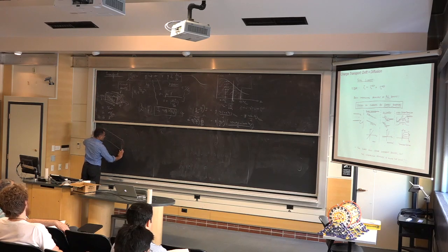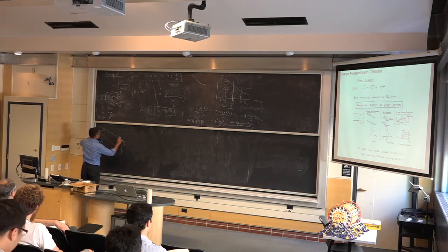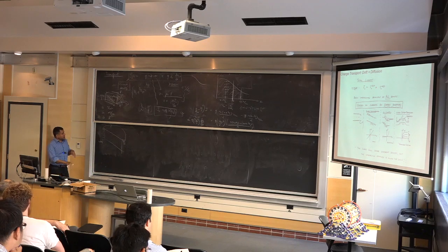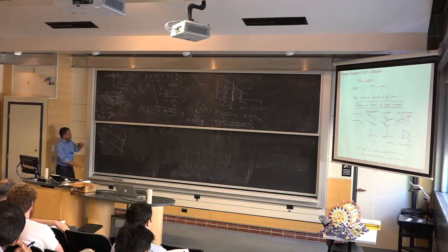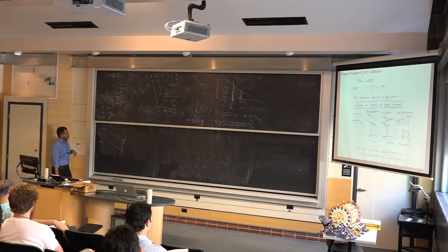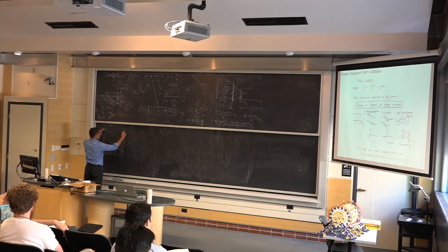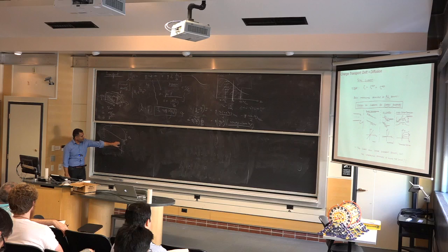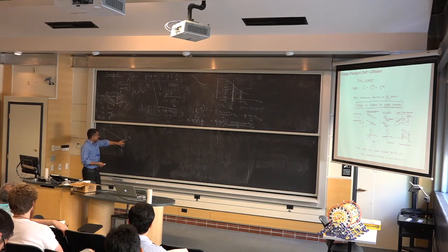And when I take two metals and I apply a voltage across them, right? Okay. Well, all I do is I actually change the levels of the highest occupied states of electrons between the two. The battery essentially just moves charges between the two. So ordinarily the two metals were the same, and when you apply a voltage, you just shift it by whatever voltage you apply across it. You just shift that energy level. And these are all, in some sense, quantum mechanical energy levels. Electrons in a metal are also undergoing all these Bloch wave functions, but they have energies and they're continuous. There's no gap for the metal.